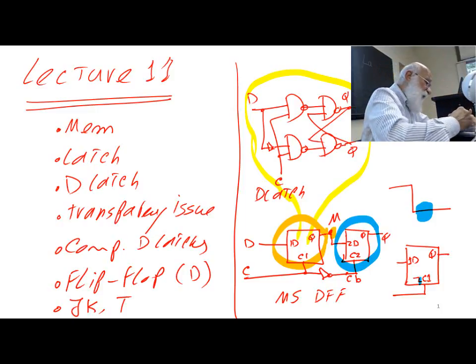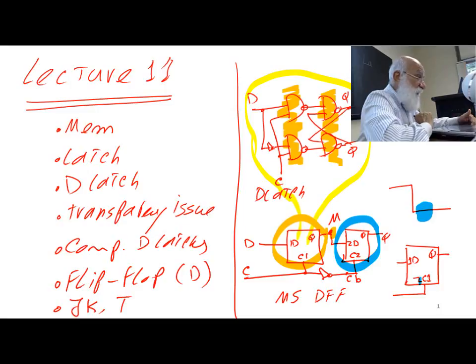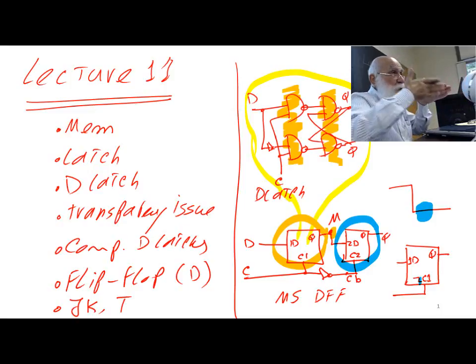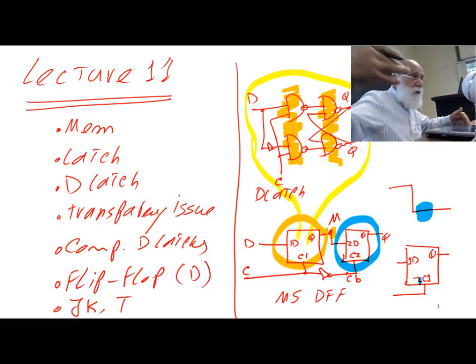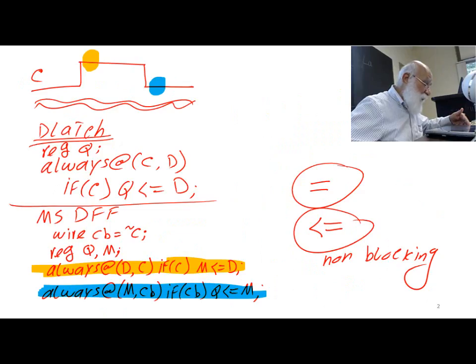Okay, so there is this logic level, and then there is this logic level. Okay, which means that for the clock to affect the Q output, it has to go through two logic levels. The question is if I can reduce that, and there are two levels here, then there's another two levels for the blue part.